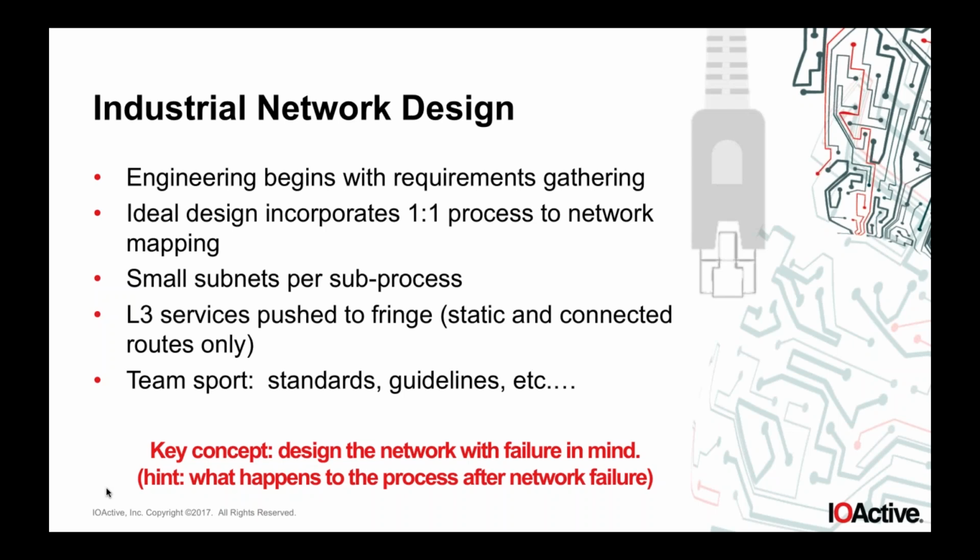Why am I using a 20-year-old layer 2 unmanaged switch if I can't be down in a particular area more than a few seconds or it's a potential safety issue? If I see those issues, or I know it's going to cause a downstream impact, then at that point we ought to be talking about redundant networking, redundant controls, having failover strategies and switches so they back themselves up, having cold spares, hot spares, warm spares, whatever we may need to make sure that we can maintain operation if there's some type of adverse condition. So for us, it's lots of subnets. I'm sorry, Brad, go ahead.